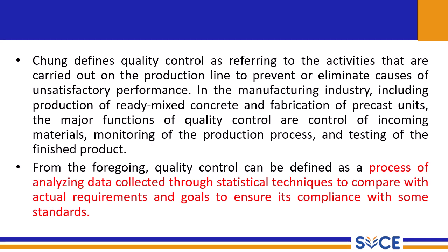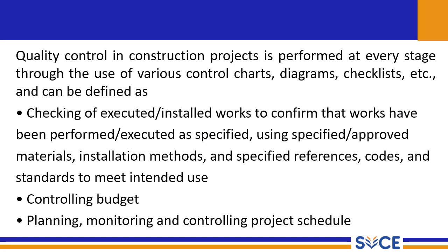So what they're trying to say is basically analyzing some data through statistical techniques and comparing it with some actual requirements. Quality control in projects is performed at the various stages through the use of various control charts, diagrams, checklists, etc., and can be defined as checking of executed, installed works to confirm that work has been performed as specified, using specified materials, installation methods, and specified references, codes, and standards to meet the intended use. So this is what we do in quality control.